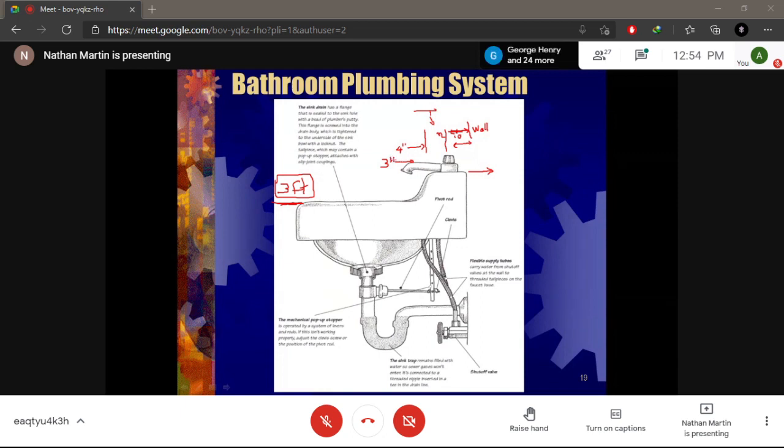All right, so any floor other than the ground floor, you are going to be using 3-inch pipe, and for the ground floor, you will be using 4-inch pipe. The reason is that this 3-inch pipe is going to be feeding into this 4-inch pipe, so you want this pipe to be able to handle the capacity of what is coming from the 3-inch pipe.